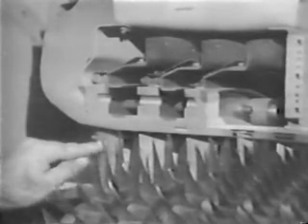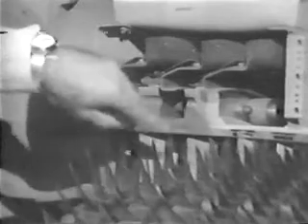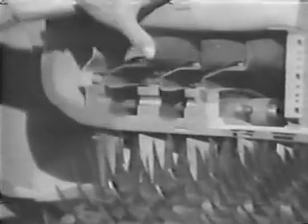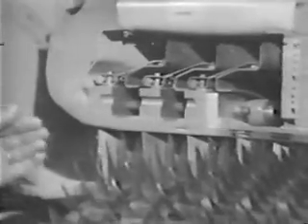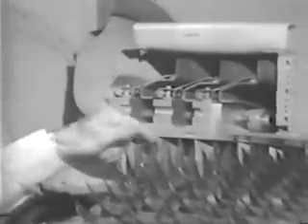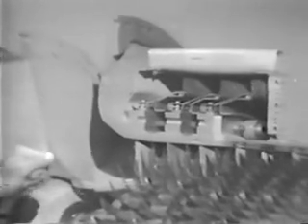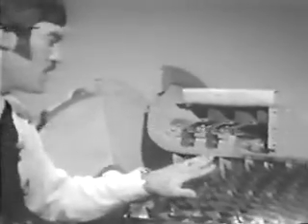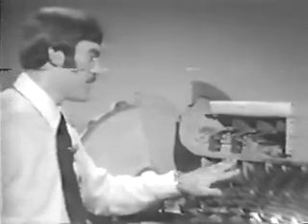The inlet guide vanes, the first stage stators, and the second stage stators are movable and change the angle of the air entering the first, second, and third stage rotor assemblies. At low speeds, this reduces the volume flow rate in the forward end of the compressor enough to allow the rear stage of the compressor to move the air without choking and causing a stall condition.